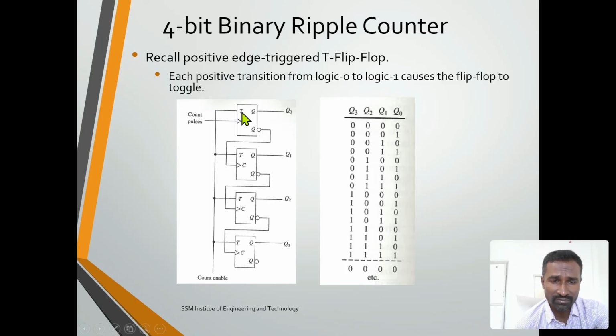Here I'm using the toggle flip flop, T flip flop. This is the 4-bit binary counter, with 4 flip flops, and the input I'm giving is T. The outputs are Q0, Q1, Q2, Q3, and the Q bar output is fed as the clock pulse of the preceding flip flop. Let's see. Q0, Q1, Q2, Q3 start at the initial state 0, 0, 0, and then 1 will come, and again 1 will come, and again 1 here. So it will automatically start increasing based on the counting operation of the toggle.